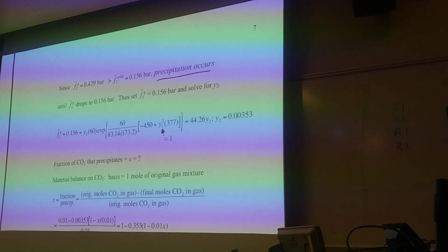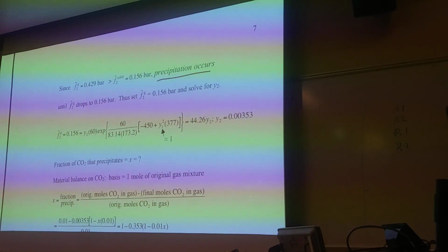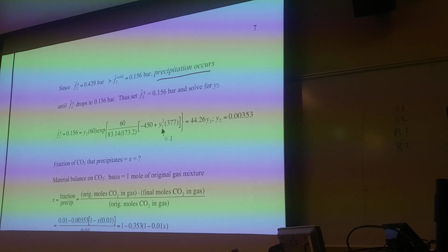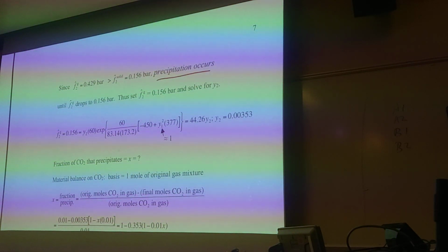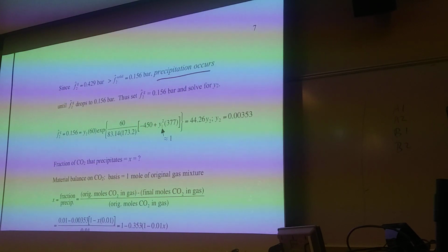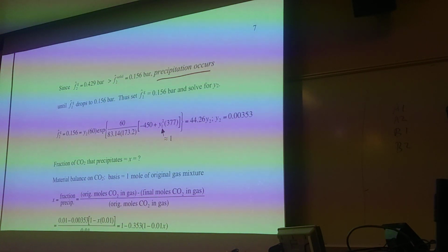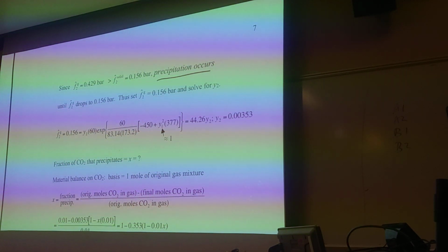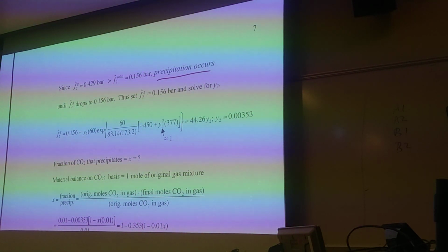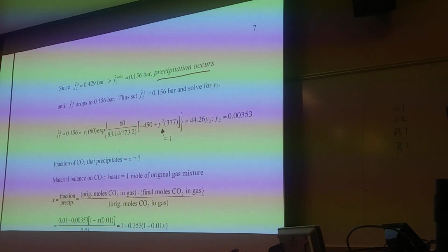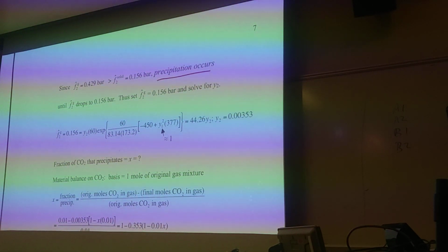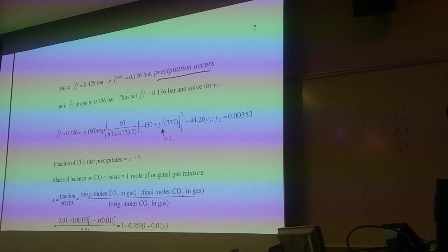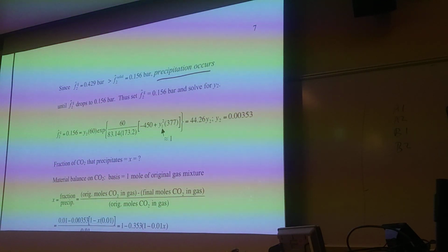Yeah, so you approximated the coefficient as 1 in this case, but in a previous problem, a couple of problems ago, you didn't approximate it. How do you know when you can approximate as 1 and when not to? Well, the guess here is that the pressure we're dealing with is 0.13 something bar, so it's a pretty darn good guess. When you get that low a pressure, essentially everything's an ideal gas. However, you're making a good point, because we have the information we need to calculate. Did anyone do it? What did you get? Like 0.998. There you go. Basically 1.